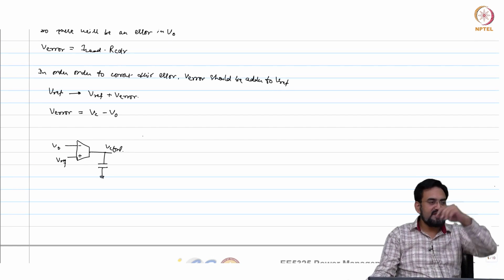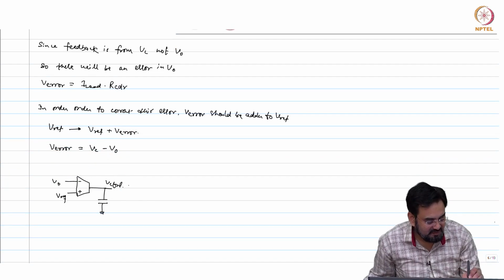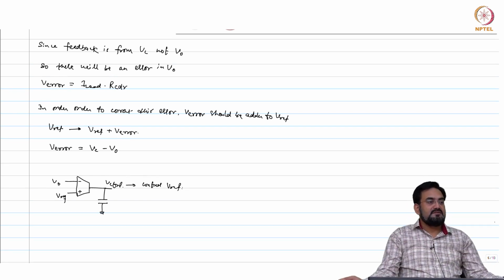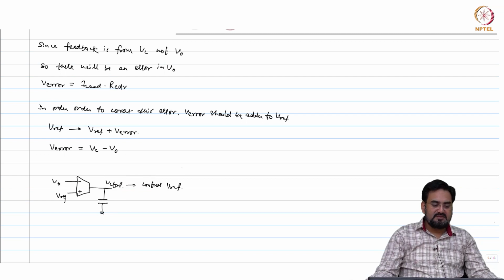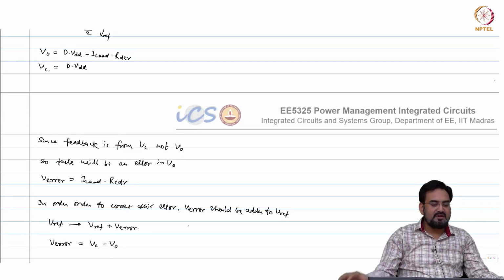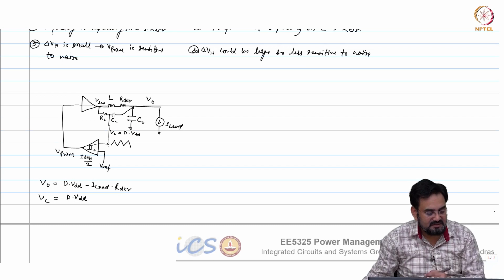So, you have another voltage feedback which is very slow, and this VCTRL will control Vref, meaning whatever extra component you want to add. So, this integrator will always force your Vref in such a way that your output is regulated to Vref. So, you need to take V out, add an integrator and control the Vref.